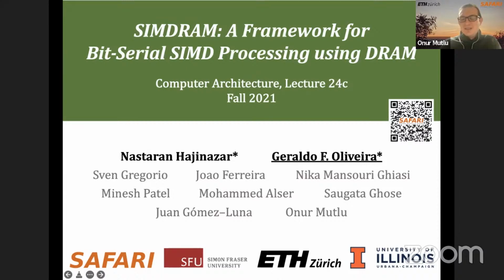Yes. I think related to the first one, coherence between the CPU and SIMDRAM capable memory, let's say. If you also have compute capable caches, then you can potentially distribute the operation that you're doing such that some of it is done in the caches and some of it is done in main memory, right? So there could be some interesting scheduling issues for operations such that they can be performed wherever data resides without flushing the data from caches, right?